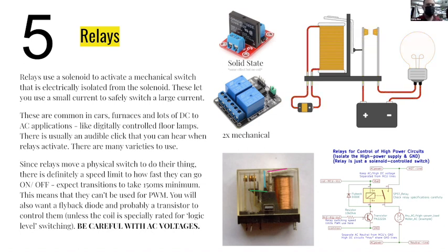I can have a transistor switch on and off in milliseconds or even microseconds. And if you look at the data sheet for a lot of things like a transistor or a MOSFET, they actually describe their switching time. And so you'll get things that are 1,000 times faster than a relay switching time, which really is at the heart of how a lot of digital electronics have been major upgrades from analog.